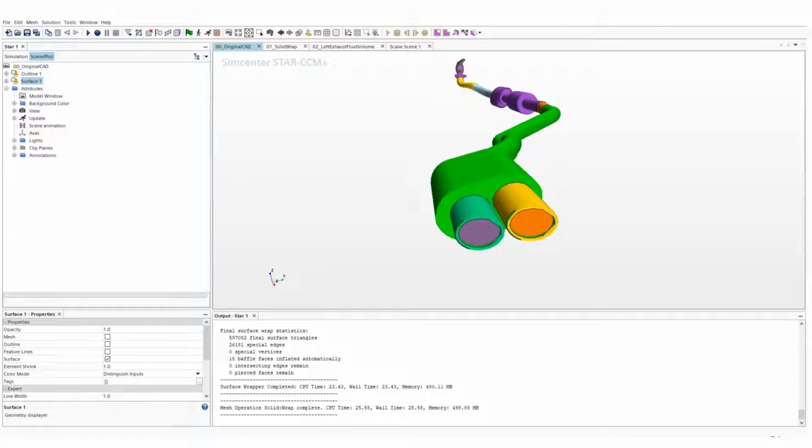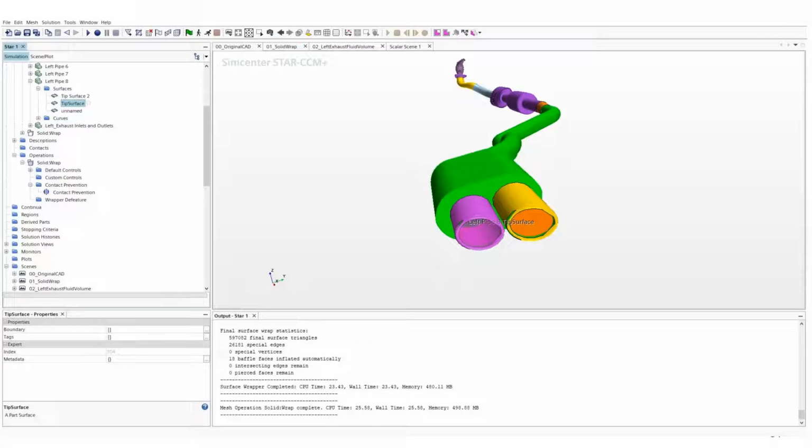This gap is pretty much critical for the vehicle thermal management team because the exhaust gases are going to be extremely hot and they're going to come at fairly greater velocity and they're going to interact with the wake region behind the vehicle. And modeling this gap between the tailpipes could be critical to understand what happens to the exhaust gases once they come out. Because of the wake region, do they rise up and hit the bumper and melt it, or what happens? So let us go ahead and understand and separate these two tailpipes.